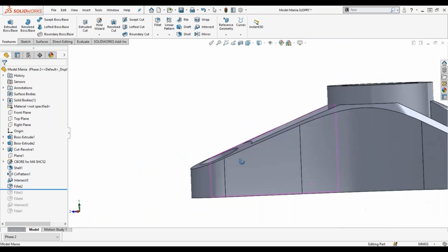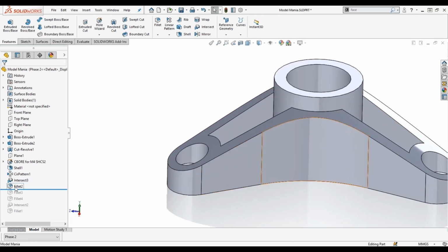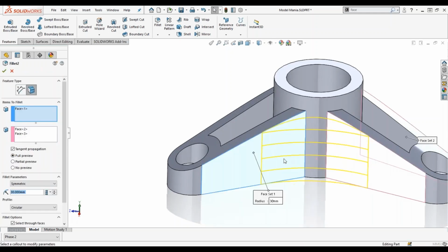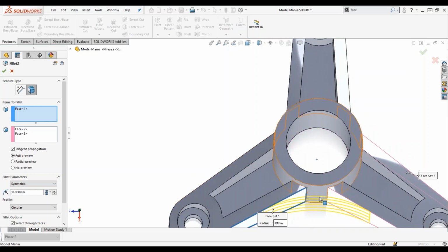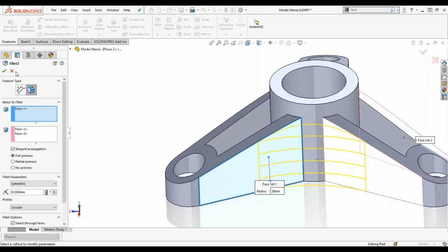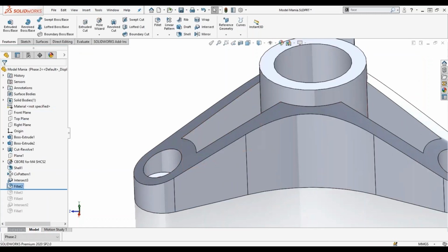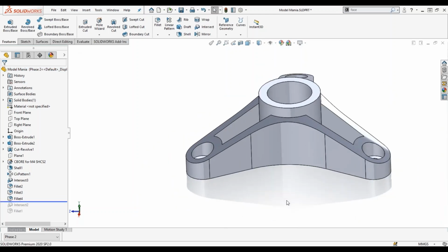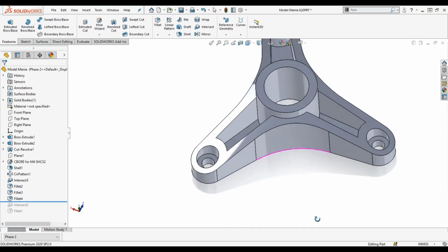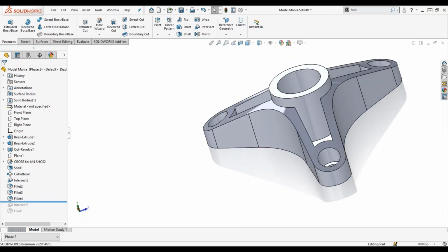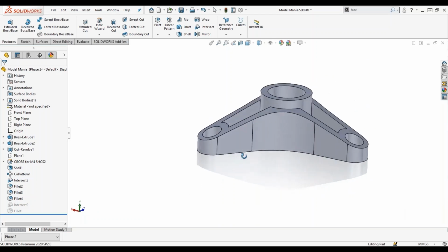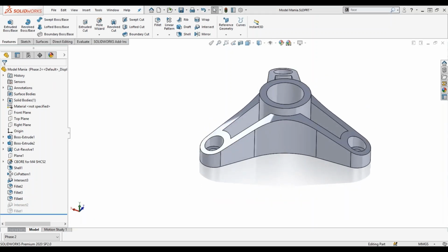So what face fillet allows is for you to just do, if I just edit this feature, a fillet from this face all the way over to this face, and it just eats up that area and fills it in for me, and I don't have to worry about it. I went from this face to that face. And again, 3 times, because you can only add 1 face fillet per time. And then that's it.